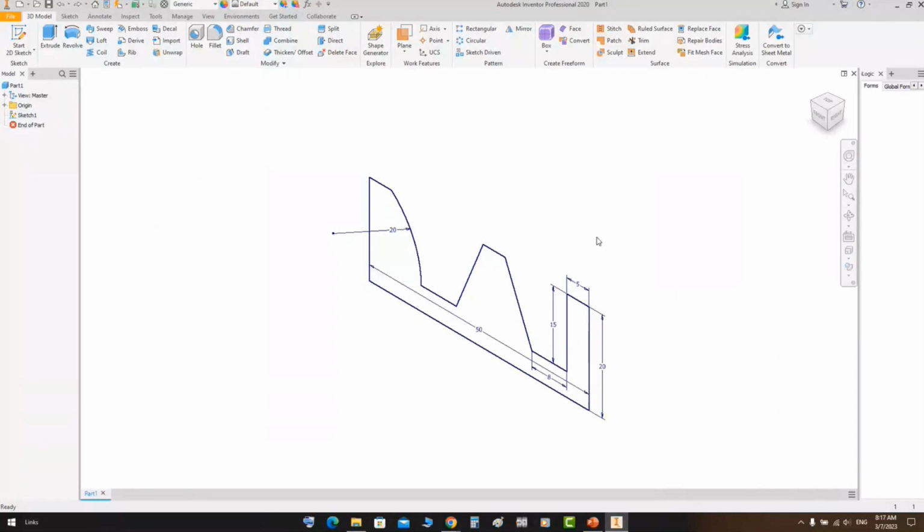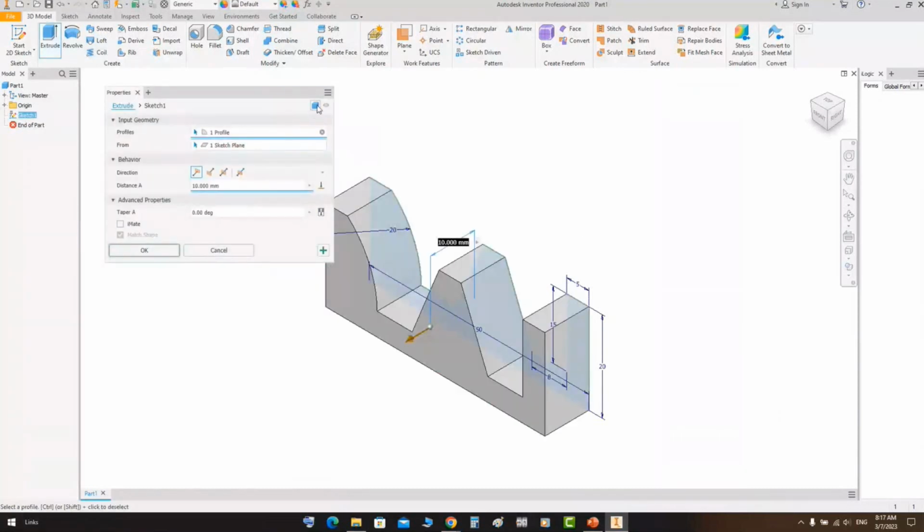session inshallah. We will discuss how to make sheet metal and how we can make ribs, common ribs. All of that inshallah we can discuss on the next session, but here I'm giving a hint for surfaces, how you can make a surface by using Extrude. Here let's keep it as a solid, and from here automatically Autodesk Inventor selects the profile.